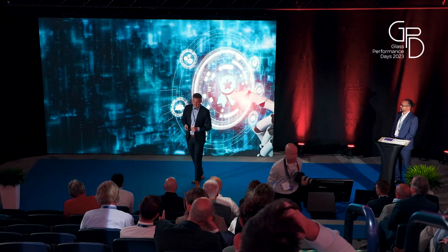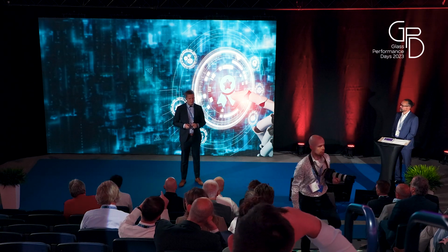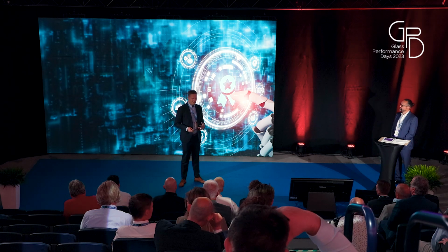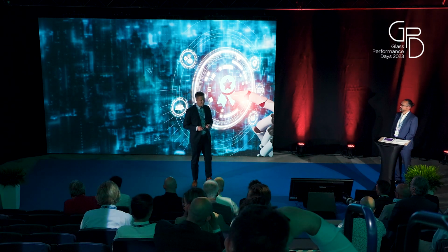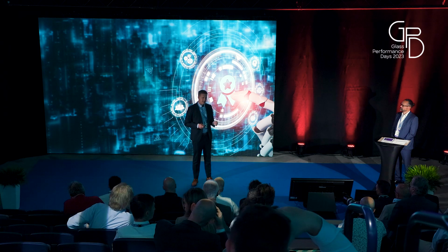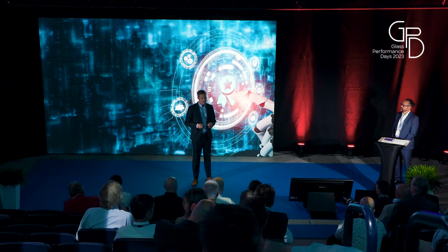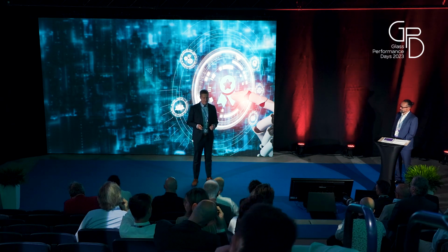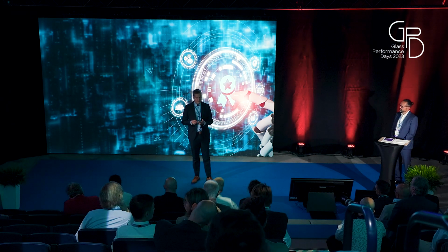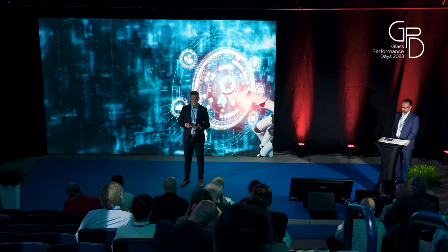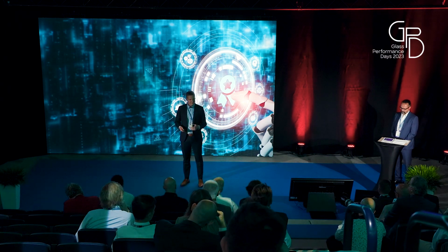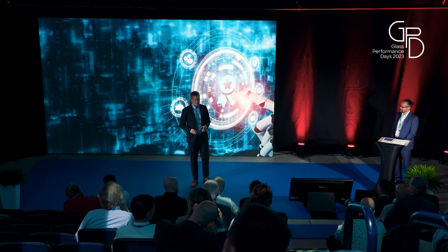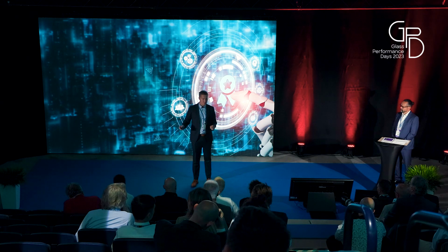And here, technological development in general really played a role. So in the beginning, we gave it a try with different kinds of, say, traditional technologies, trying to detect where the haze is located. The biggest problem there was that you have all kinds of things visible on the glass after tempering. Maybe you have some fingerprints, some marks from the Kevlar in the chiller, some other dirt, dust, etc. And it's very, very difficult to distinguish what is actually white haze and what is, for example, a fingerprint.